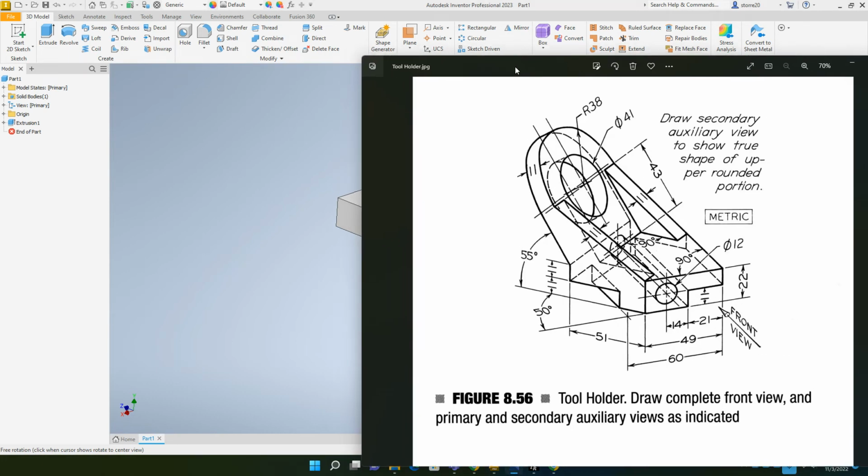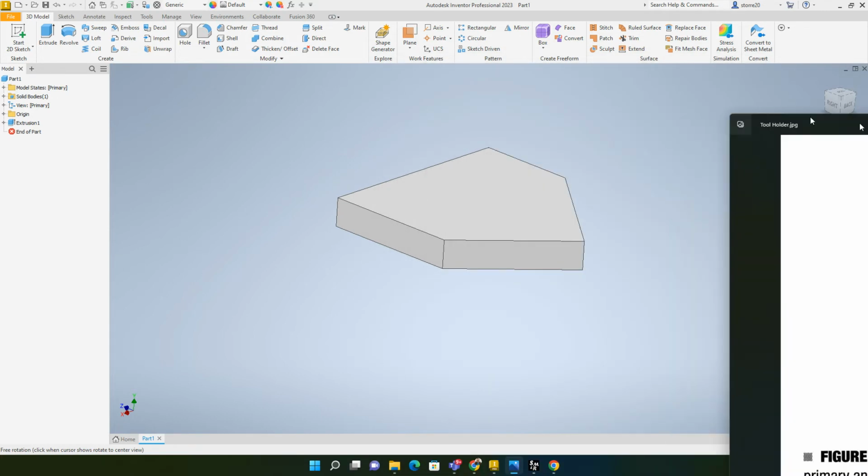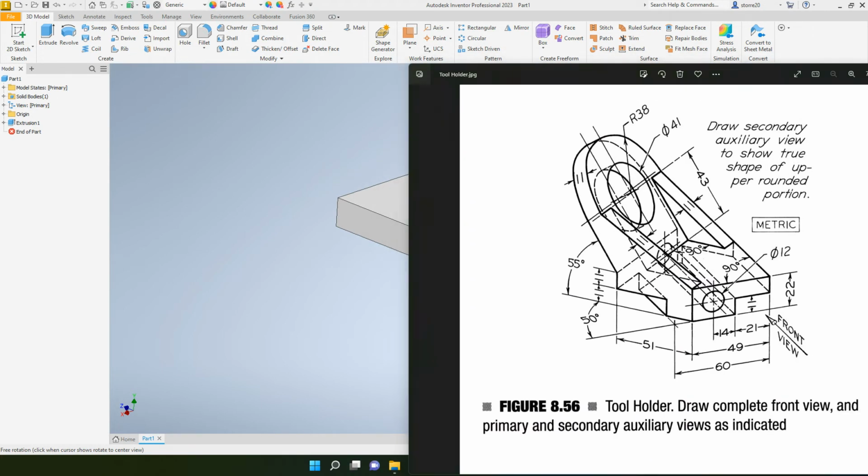So the other things that I can do, it doesn't really matter which order you go in, but what I would do is I would actually create a work plane. Sorry, I forgot what that term was. A work plane along this edge at an angle of 55 degrees to then sketch this part, where I would sketch this line and this arc. I would sketch those all in one sketch, by the way, off of this one work plane, and then extrude that one 11 millimeters, like it says right here. And I would get this whole back feature on that back surface.